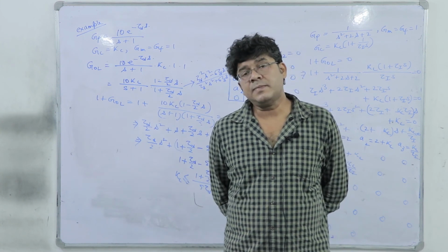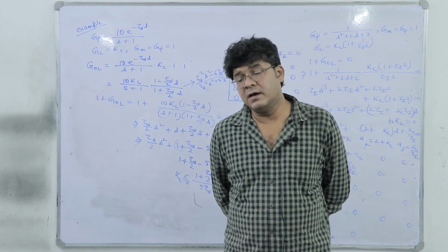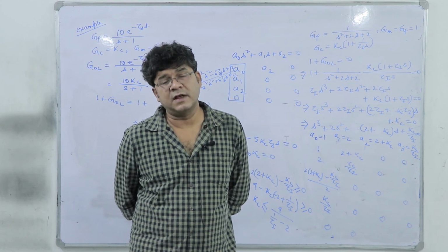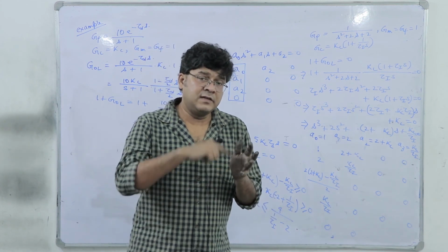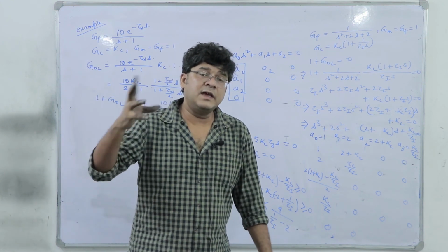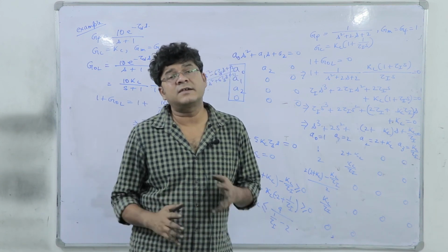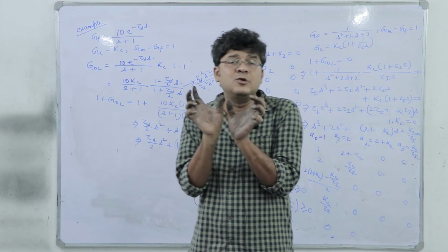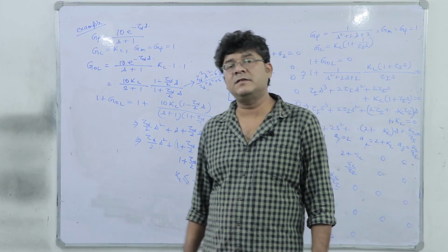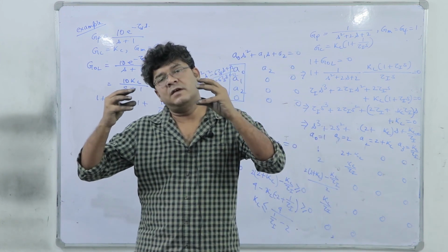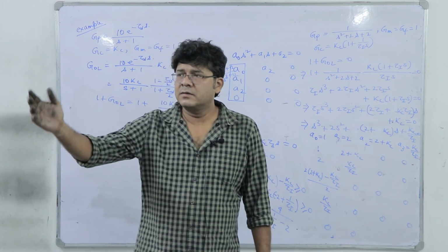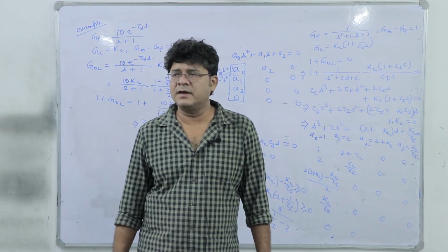So, there we have to conduct experiment with the prototype small scale model distillation column, and from there we can fix the transfer function. So, if I give some frequency response or this oscillating input, then we can reveal some of the hidden characteristics of this transfer function, such that, say it is a multi-capacity second order process, and the two poles of these transfer functions are very close to each other, okay. Two poles of the transfer functions are very close to each other.